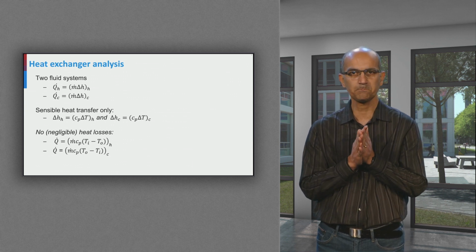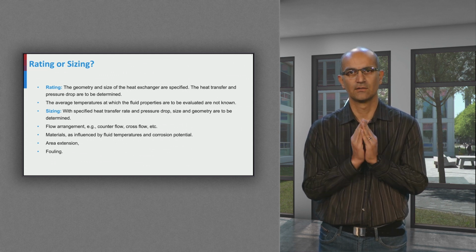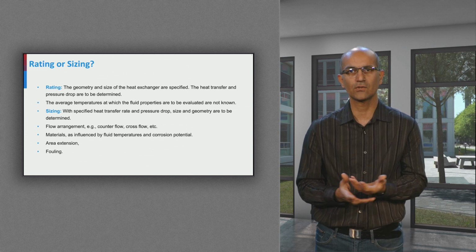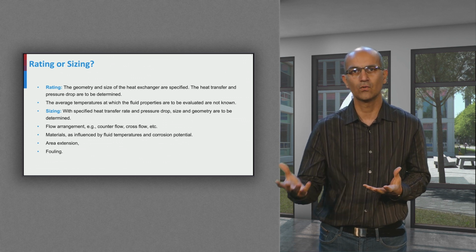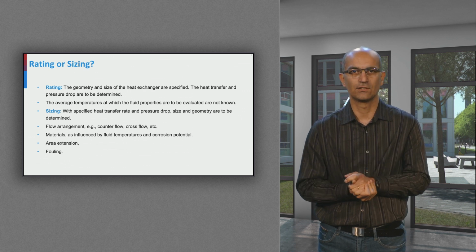For an existing heat exchanger, like the one in my office, sizes are fixed. The duty of the heat exchanger is usually prescribed, and we can calculate the air or water temperature if we have enough information. That is, we'd rate the heat exchanger.